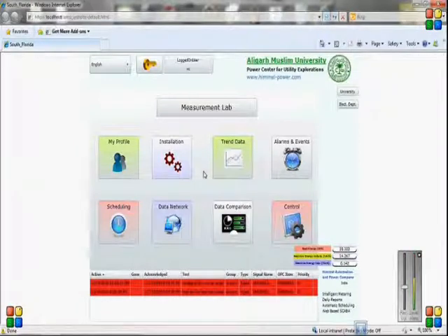These things can be applied to water heating, air conditioning, outdoor lighting, pumps, or watering facility. Why is scheduling important? Scheduling is important when you have the chance that you will reach the peak loads. To avoid the penalties for going above your connected level of allowed load, scheduling is a very powerful tool to cut off the peaks.